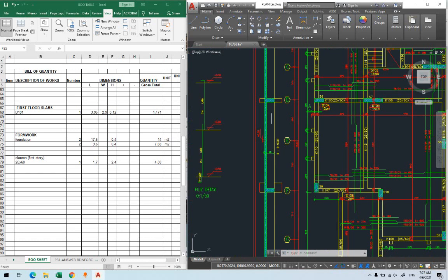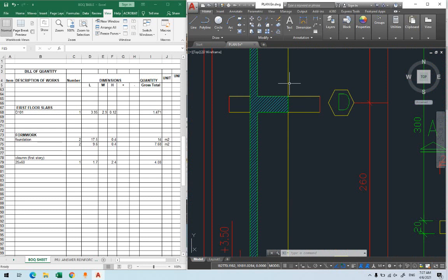Let's check something which is interior. Doesn't matter, yes. Even if you have a wall under the beams, remember the beams will be cast, then the wall will be placed. Now I'm not talking about if you don't have column. In some systems you don't have column, they just have a wall. Yes, they will create the wall first, then they will put the formwork for the beam. In that case you don't have the bottom of the beam. Yeah, in a small house they will build the wall, then the beam will come over the wall. So in that case you only have the two sides of it.